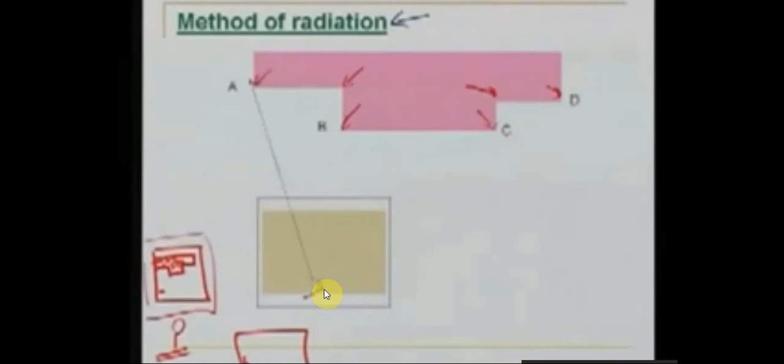Next, we will keep the alidade about point P, and we will sight point A, and then we will draw a ray against the alidade. So I'll keep my alidade at P, and I will sight A, and I will draw a ray like this on my sheet. So this is my sheet, and this is the actual ground.